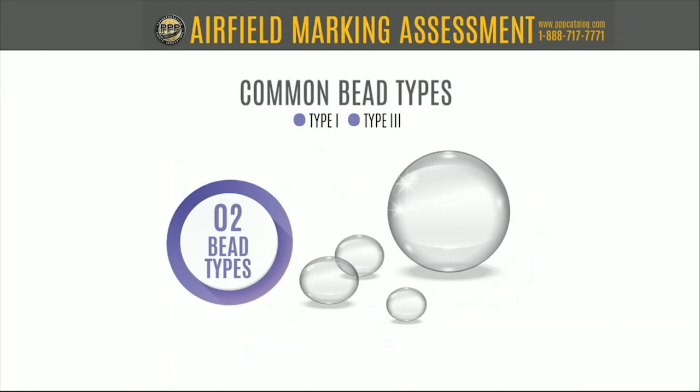I think the type 3, you'll see here in just a few minutes, performs better from a reflectivity, nighttime visibility standpoint. It performs better initially and over time, but both certainly can be applied very well and perform very well.